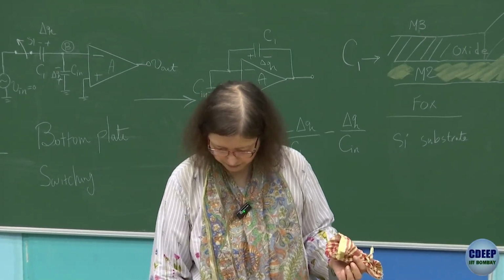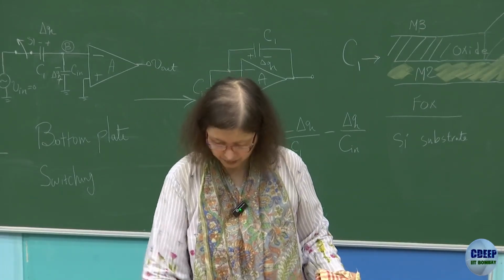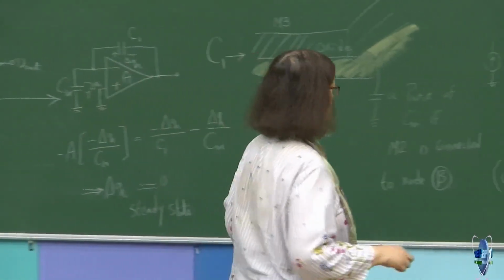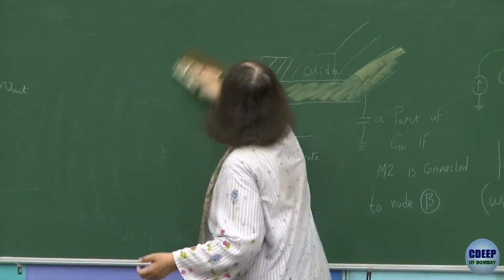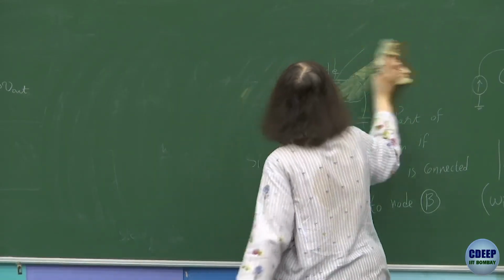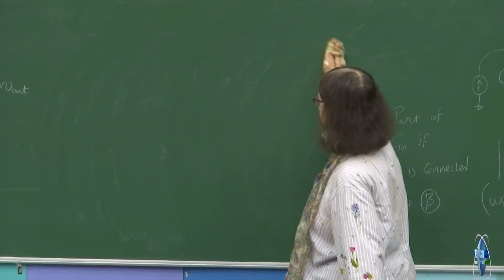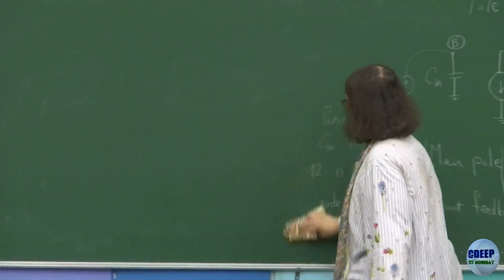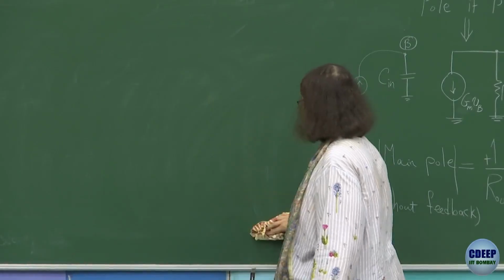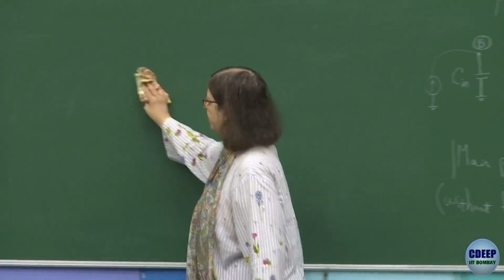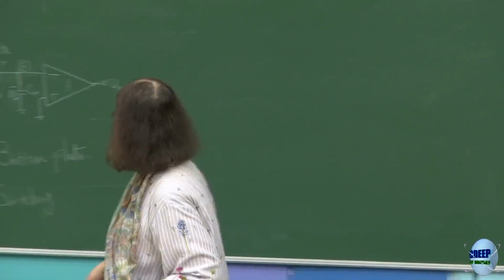The speed, of course, affects the precision, but it's not only speed. It's also the effect of the gain of the op-amp, that we have not discussed. Let's discuss that as well. And now we talk about the last part. This kind of analysis is common for all the circuits: speed analysis, effect of parasitic capacitors, charge injection, which is usually taken care of by bottom plate sampling, and the effect of op-amp gain.